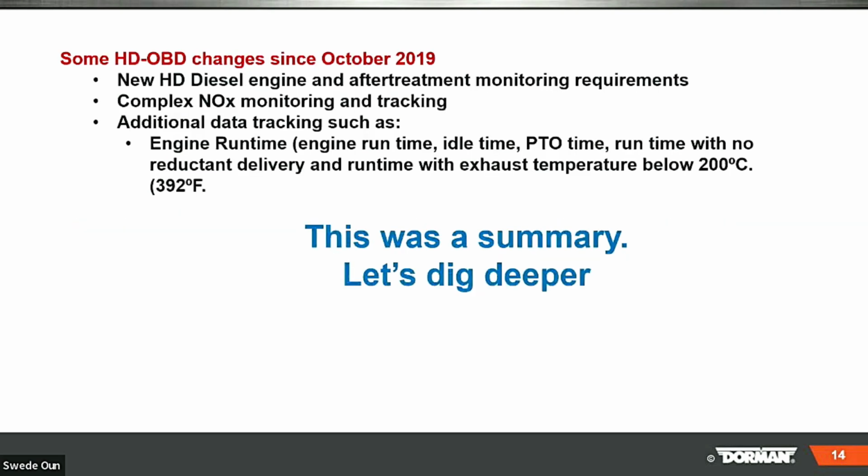Some heavy-duty OBD changes since October 2019. New heavy-duty diesel engine aftertreatment monitoring requirements, complex NOx monitoring. I did all that stuff with emissions the last 3 months. And boy, I've got to tell you, this is where it all comes down to, why we have this, especially OBD, emissions.